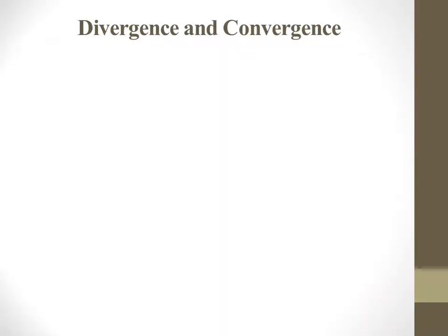So the SFC schema is processed from the initial step, which becomes active immediately when the program unit is called. Then the activity of steps is distributed through direct links when the corresponding transition conditions are met.